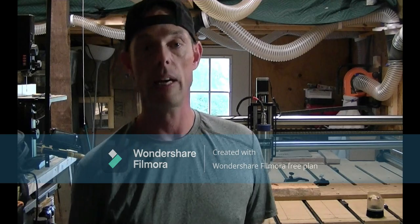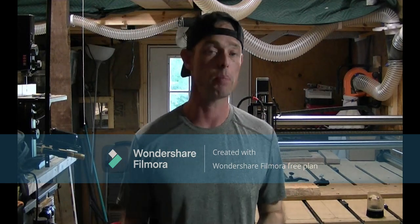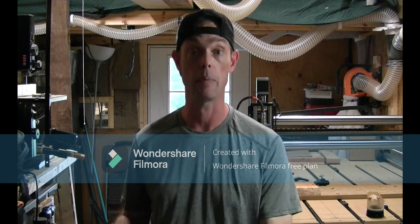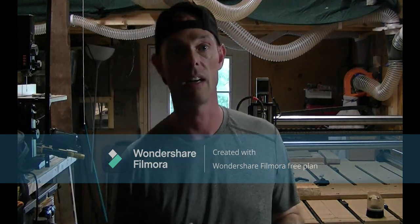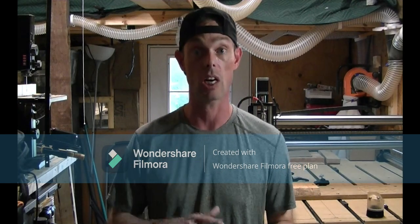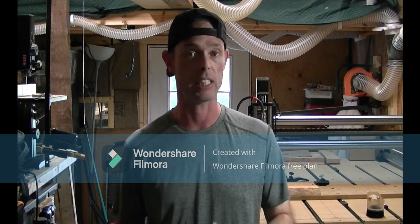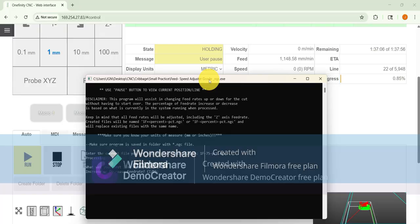Increasing or decreasing the feed rate comes in very handy if you want to start low. I usually start low and work my way high, just based on different types of materials, based on different types of bits and companies of bits that I buy from. So just so I can get the sweet spot, I can work my way up rather than start high, break a bit, and have to start all the way over, or run into the edge that I wasn't accounting for because I didn't see it when I ran the preview.